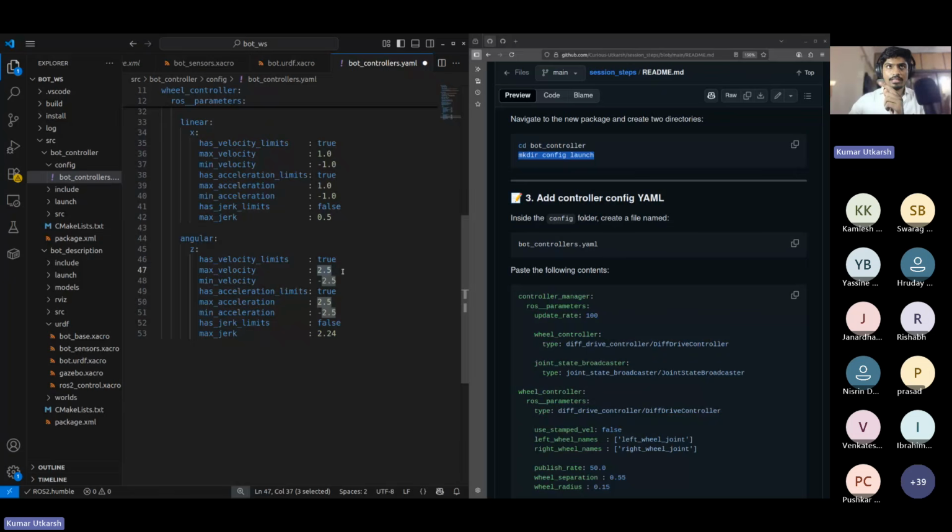The motor rotates at a certain RPM. The encoders measure it, then reverse calculate at what speed the wheels are rotating, and send it back over serial to ROS2 control.